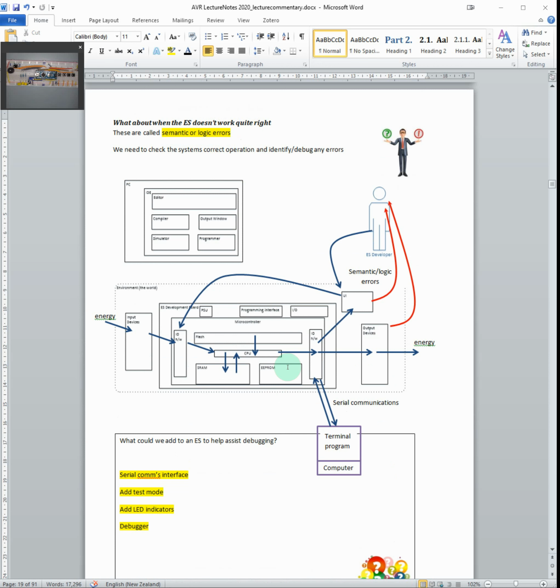It has no bugs in terms of its operation, not its syntax, and therefore it's what's happening back here in the IDE, but what's actually happening here in the board. So for instance, on my little board, I've got a thermistor which converts thermal energy into some resistance value, which is transferred by a voltage divider into an I/O hardware, and it's read by an analog.